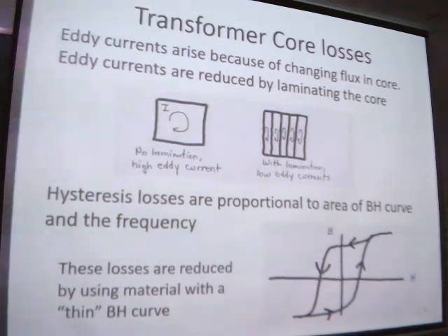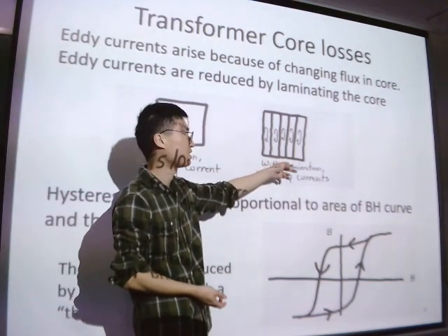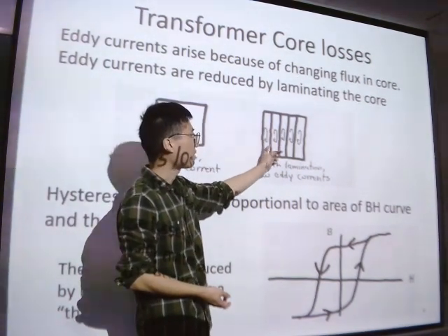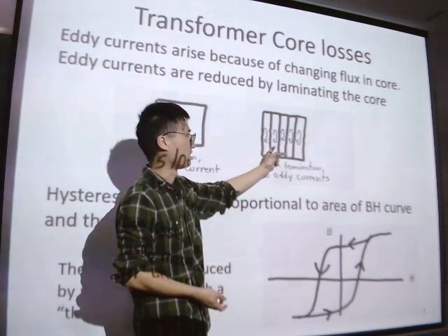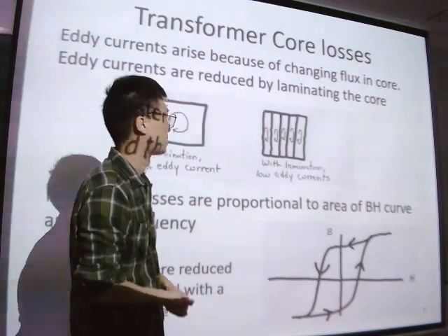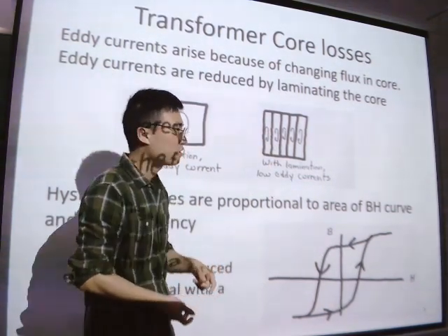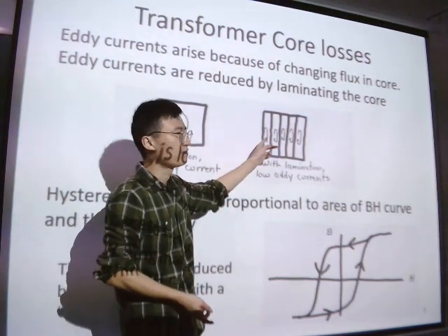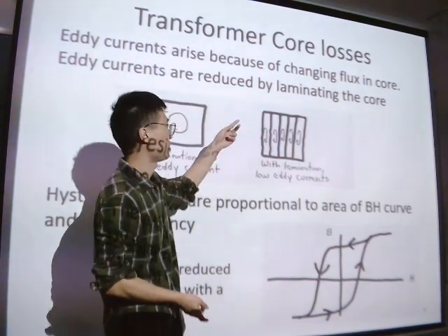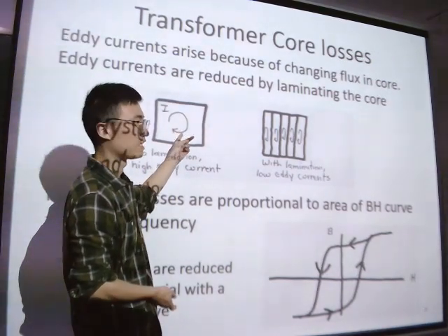It may be here to be 5 slices. Okay, 5 slices. The eddy current is still released in each slice, or in each lamination. In each lamination, however, it will become much smaller, even compared with 10% of the original eddy current.